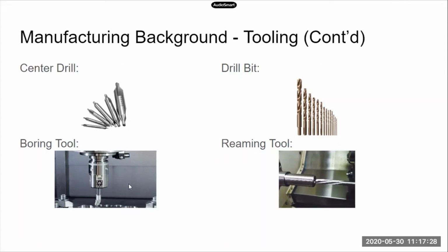They have letter drill bits. There's a lot of different types. Generally, if you're making a hole, you want to make sure that it falls within a standard drill bit size. Otherwise, you're going to have to do some weirder stuff.